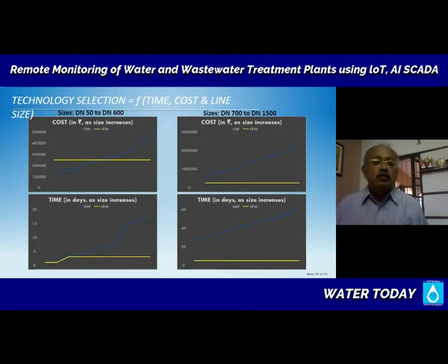And this one here looks at different technologies from a cost perspective. The two main technologies that we are looking at are electromagnetic and ultrasonic technology. Both are quite reliable. Electromagnetic, of course, is a very, very robust metering solution. And in terms of cost, you will find that up until you are measuring in pipe sizes of, say, 300, 400 mm or less, electromagnetic flow meters are very efficient, cost effective, accurate. But as the size increases, the ultrasonic meters become very, very cost effective.